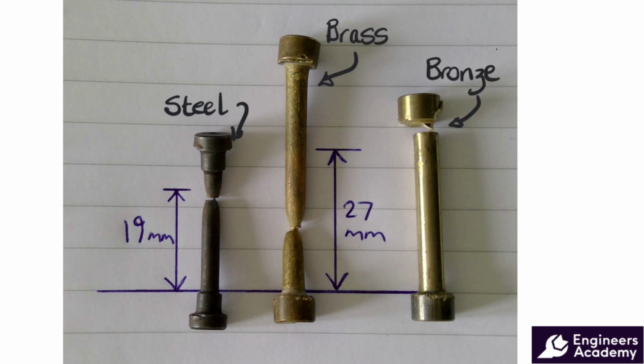By examining the breakage areas on each of the test pieces, we can gather some information that isn't quantitative because it doesn't have numbers, but it is qualitative. So for example, looking at the sample on the right hand side, we can see that the fracture is clean without any stretching before failure. It's not got what we would call necking. This brittle fracture would indicate that the material is very brittle, where it has suddenly snapped without stretching beforehand.